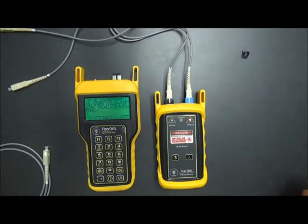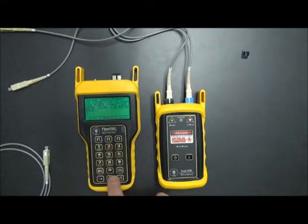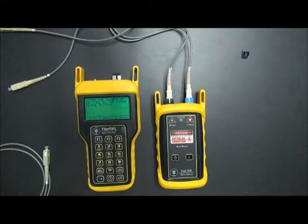So in this fiber link right here, we have two connections, one on this side, one on this side. Okay, so in our link wizard, we're going to enter the number 2 simply because we have two connections. Now the next question is the number of splices in the link. Usually in multimode fiber, there are no splices. That's typically not something that's done. However, with newer types of connectors such as Unicam or other no polish, no epoxy type connectors, there is actually a little mechanical splice produced inside the ferrule during the termination process. So it is okay if you want to enter in a splice for each side.